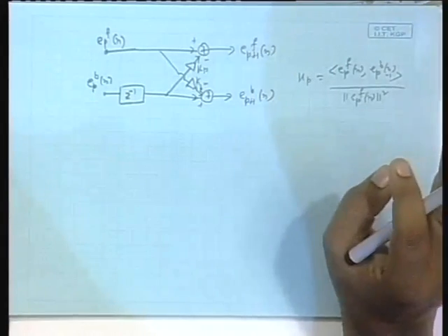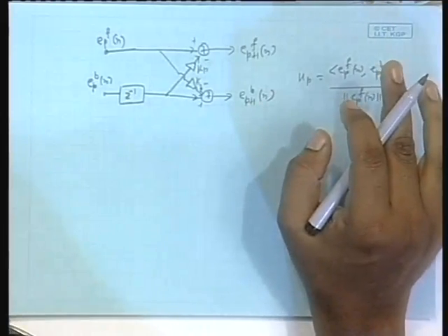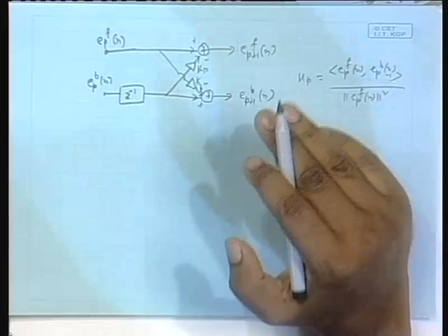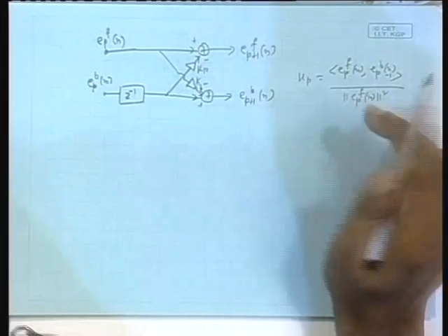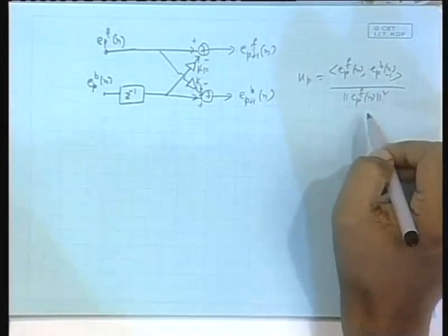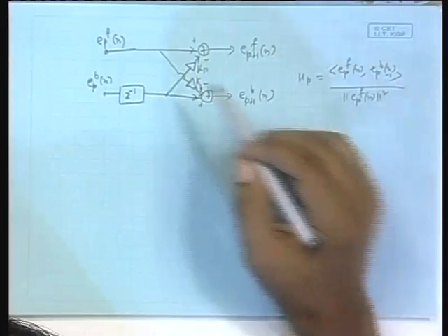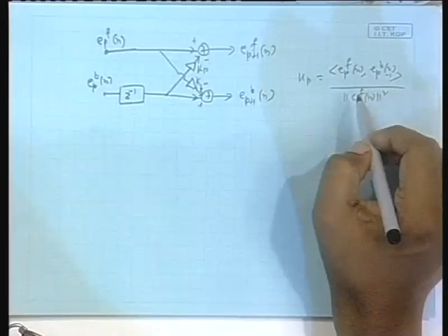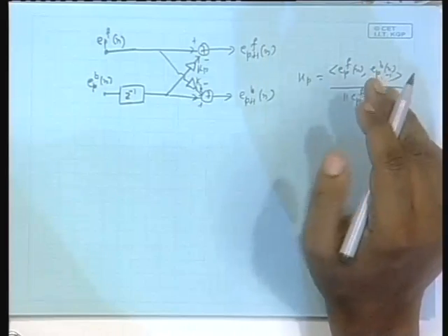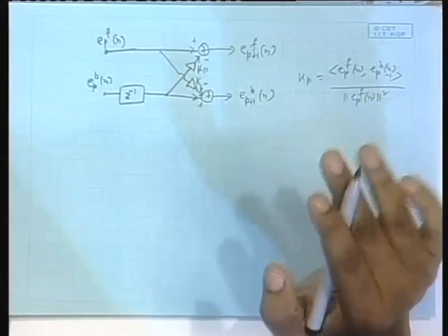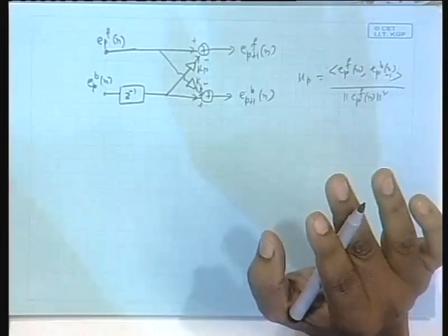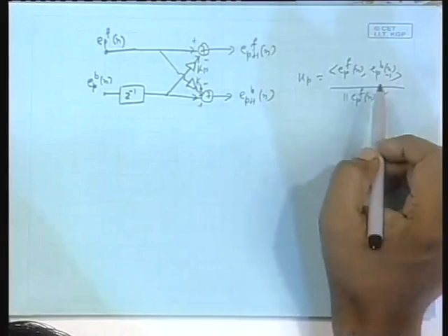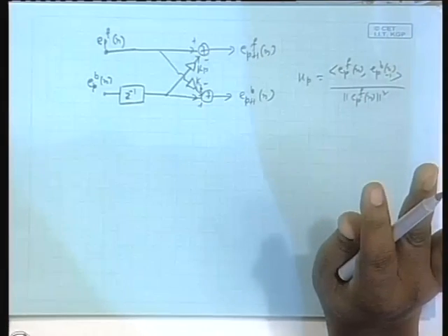Now, if it is stationary and the statistics is known, you can get all these things in terms of the correlation of the original process xn. You can recursively update this norm square, and also using the predictor coefficients you can evaluate this numerator, which I called delta p. So essentially, given the autocorrelation values of the original input process xn, you can find out this Kp, right.